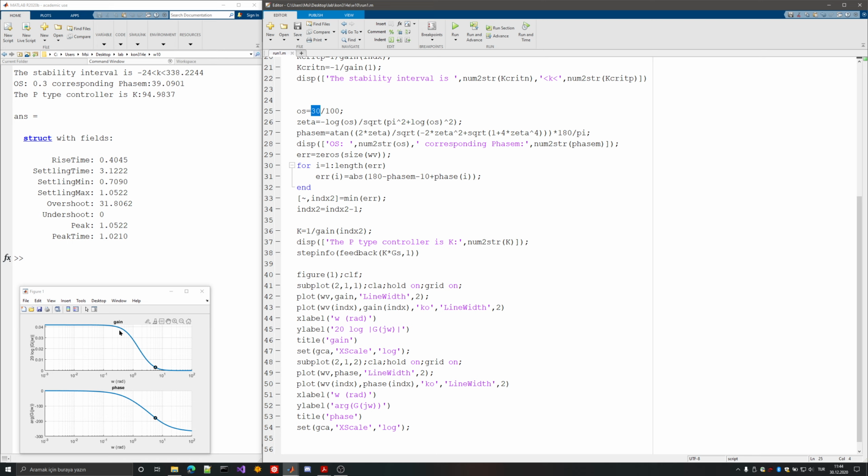but then the question is, why would you use the frequency domain for time domain criteria design? If you want to design settling time, overshoot, these kind of properties, then the time domain approach makes more sense, because you're starting with a settling time and overshoot. Here you're kind of manipulating the frequency domain data that you have so that you get a design.